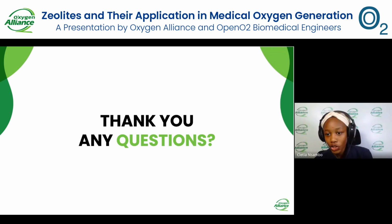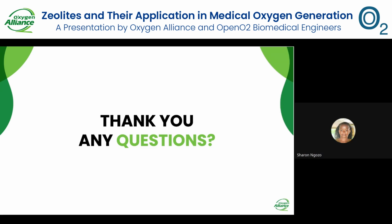We also have another question from Hilda Bugingo, and they're asking which tests are done besides the leak test to ensure that the zeolite canister is well connected. Yes, Sharon. To add on what was stated in the presentation, the leakage test is the test that you do when you've installed the sieve bed back into the concentrator. But before installing the bed back into the concentrator, if you've refilled the bed, it has to go through the pressure test.